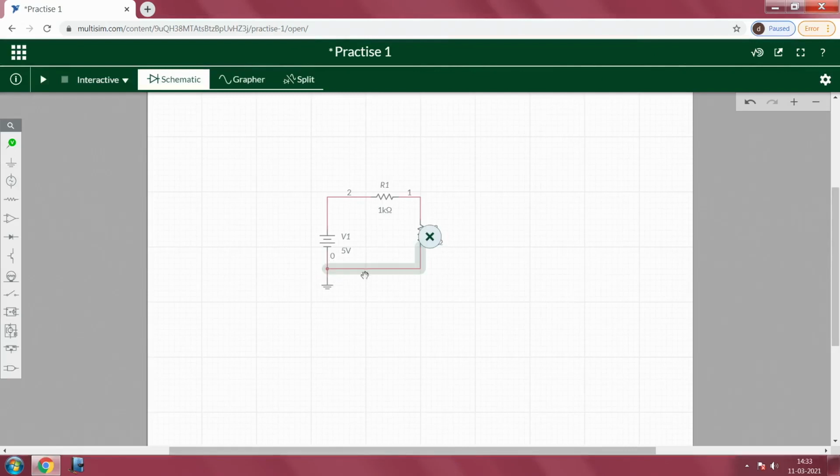So, after wiring it, the next step is changing the values, in case you require to change from the default values. I would like to change the voltage to 10 volts. Okay. Then this resistance to be of 10K. So, even this resistance I am selecting as 10K.